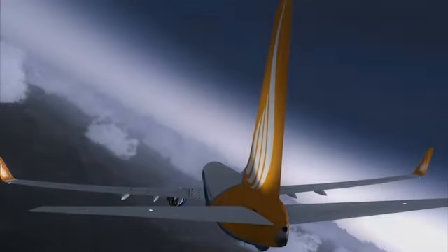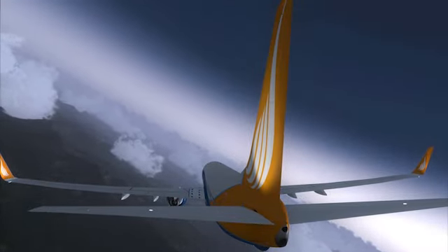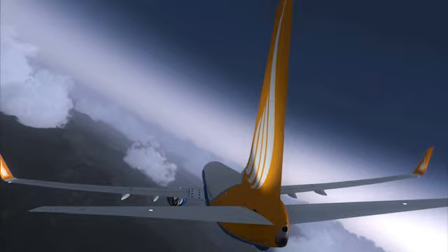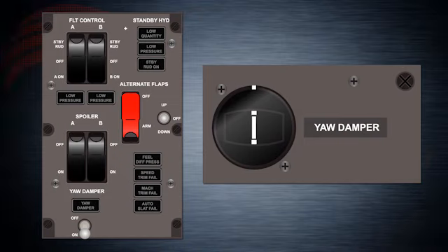This not only keeps the aircraft flying smoother, but also keeps the passengers comfortable. Otherwise, you'd have a lot of people getting constantly wobbled about by Dutch roll. Many would be surprised yaw damper does belong in this lesson, as it is an Autoflight subsystem. It's dependent on the sensors that are a part of this system, and it also looks ahead to smoothly transition from one control movement to the next.